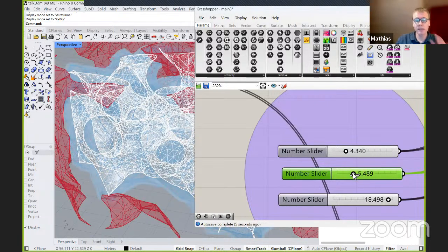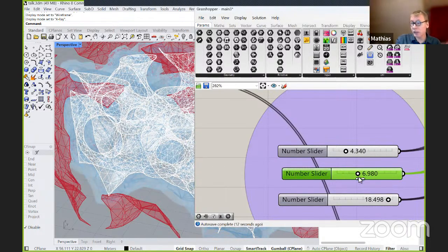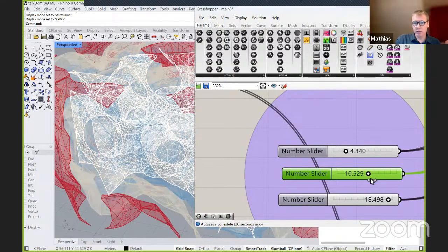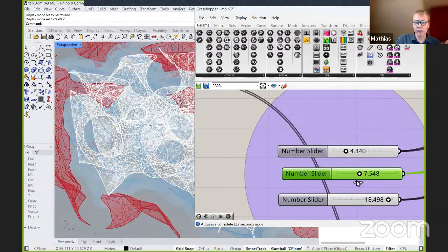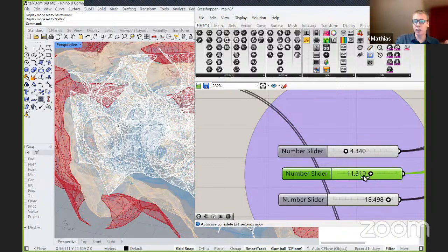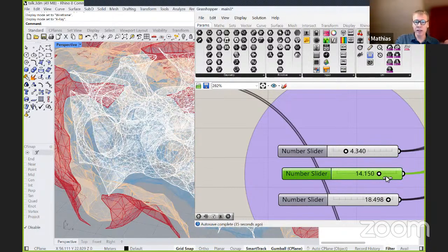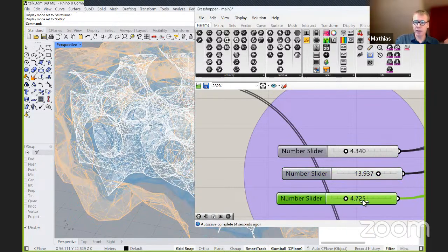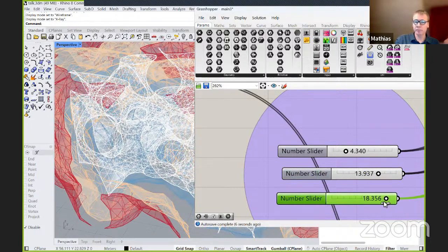So as you can see, we are isosurfacing a certain distance field from our initial mesh, all right? And then, because we want our life to be colorful, we are hitting this with a color gradient, and the color gradient just encodes the distance from the initial mesh. Okay, so I hope this is more or less clear what's going on here. We just have 3 meshes that give the initial mesh a thickness.